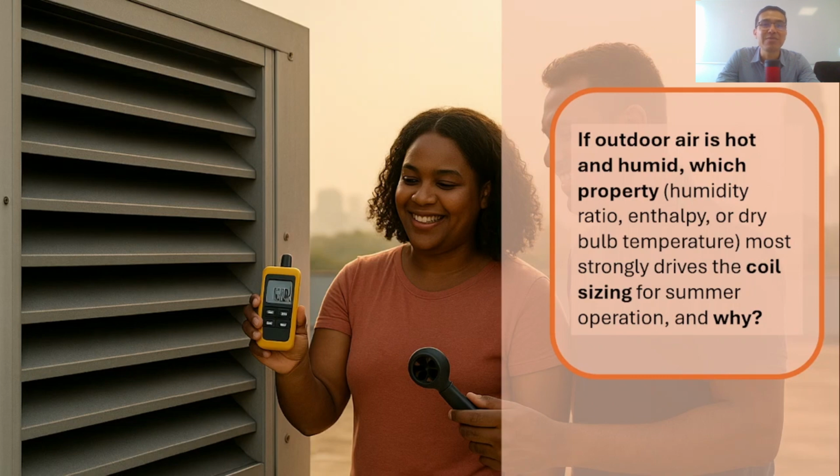Outdoor air with high humidity ratio raises the ventilation latent load, which adds to the coil's job, even at moderate sensible conditions. As we hold some conditions fixed for comfort, it is often the reduction in humidity ratio, not just the drop in the temperature, that sets the coil exit state, and therefore the coil load. So in the humid places, we are going to have to remove more latent load, no?